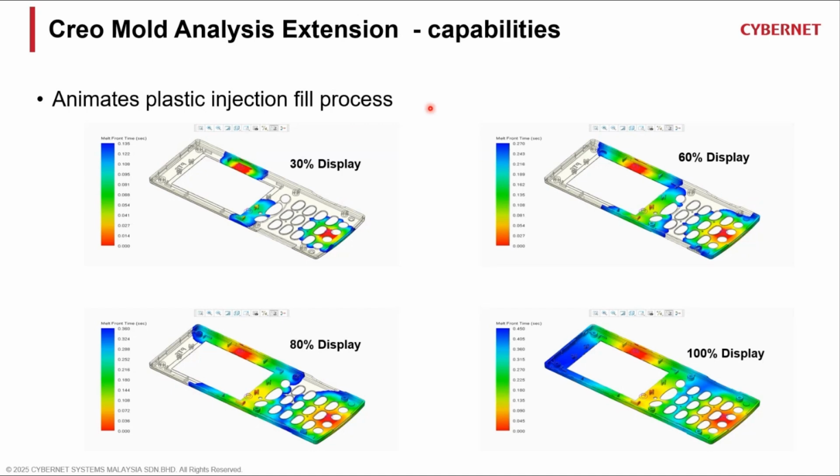I can animate it, so you can see how the mold flow looks when it reaches 30%, and 60, 80, and 100% when it's fully filled. The purpose is to see whether it's going to fill completely or whether there is any air trap happening.